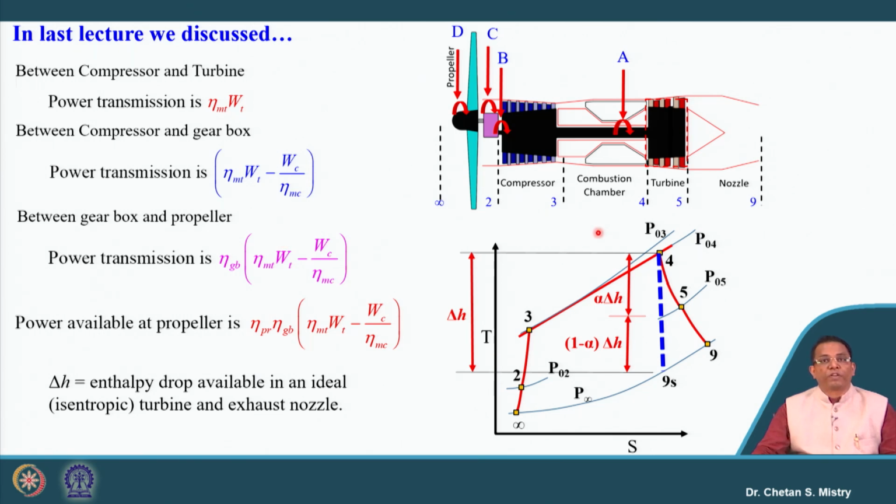A very important aspect we were discussing is the transfer of work. In this case, the turbine is used for rotating the compressor as well as the propeller, and what amount of work is transferred in both cases is a little tricky to understand and calculate. One more thing is that in the exhaust we have a nozzle, so this nozzle also contributes some amount of thrust generated by this engine.